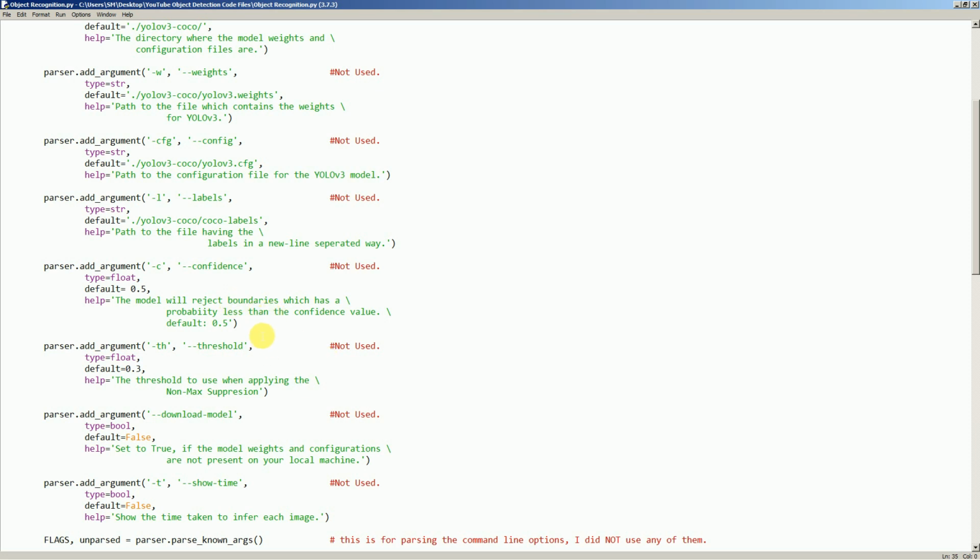What I wound up doing was I would send the character, it would flash, and that would tell me that it actually read the character. Then I would take that 41 and multiply it by 10 to get 410, let's say, or add 100 to it. Then I would have an if statement that would trap for an integer 141 or 410, and that would flash 5 times or stay on solid for 2 seconds. And then I knew I actually got the character that I sent.